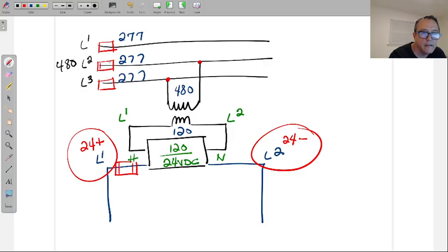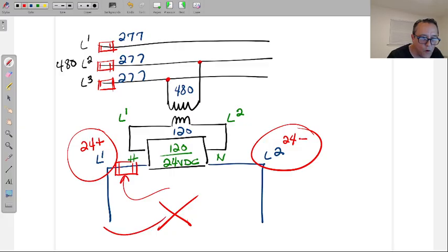All right, these are our fuses. Almost always we will have a control fuse that is before L1 has power. All right, and this control fuse, again, it is 24 volt DC down here. So we're not worried about power coming this way into the circuit.